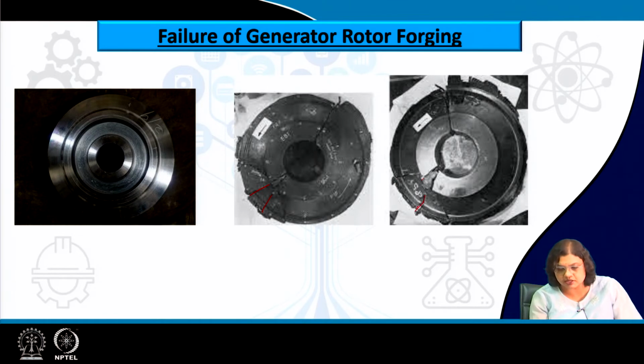So, this signifies that this is a brittle mode of fracture. We can see that failure has occurred at several locations. So, certainly this signifies that this is a brittle failure, and hydrogen has been already entered into the system at several locations, which led to this final fracture, and this is again an incident of cold cracking. So, suddenly during the service itself, after several years of work, one fine morning it just fractured on its own.